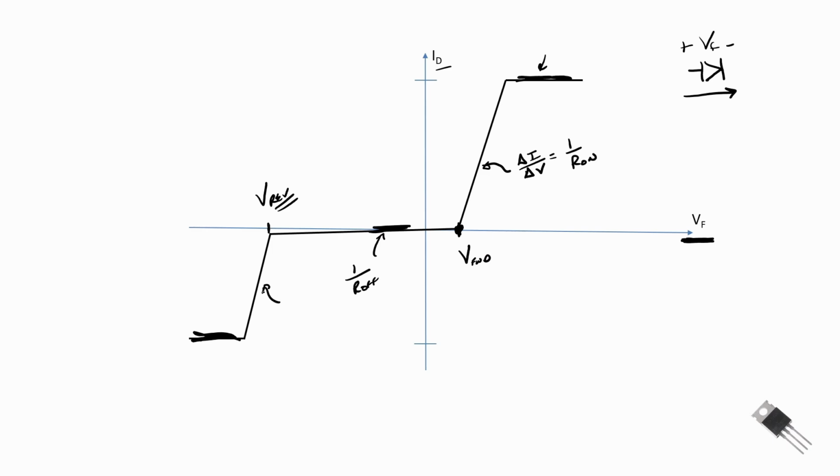And this slope is 1 over our reverse resistance when we are in breakdown. So that dynamic resistance is represented by that slope. If you do not specify this in the model card, it will revert to R on, and so those slopes will be the same. The epsilon in the forward controls the smoothness of this knee. It does a quadratic fit.